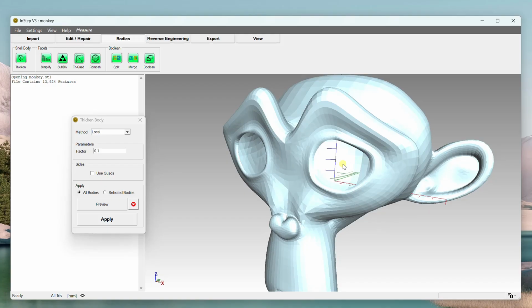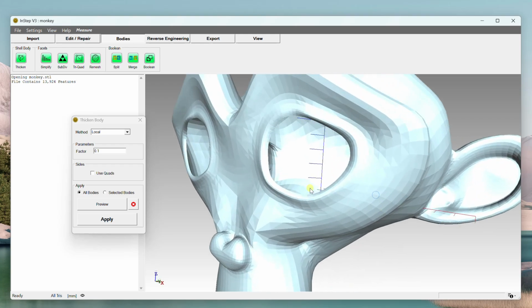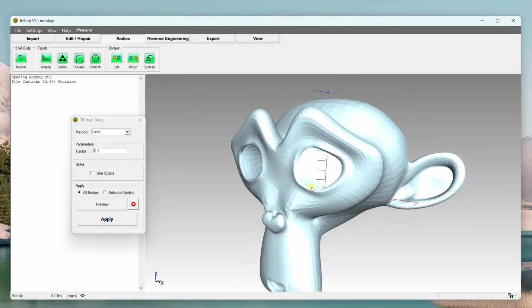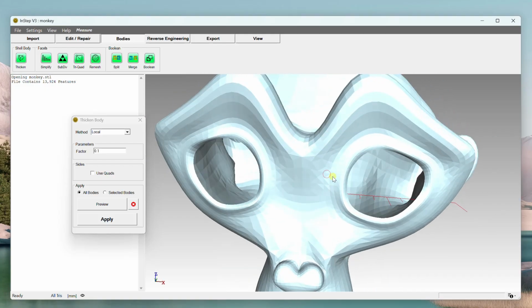Effectively what's happening within the algorithm is it limits that distance from the near plane to the far plane, and there's a number of divisions within that where it can distinguish what is one side and what's the other. So generally you're not going to have to touch that, but if you see these artifacts pop up and you want to work with data that's going to trigger that, then that's a way of doing that.